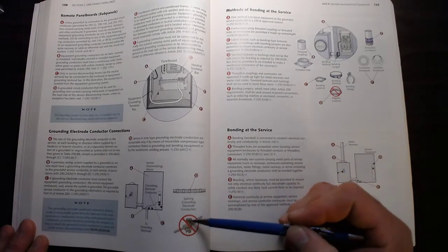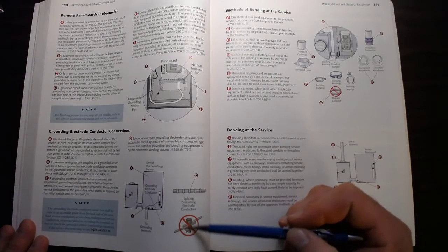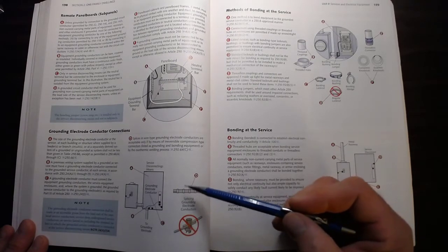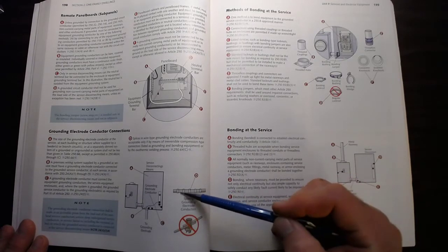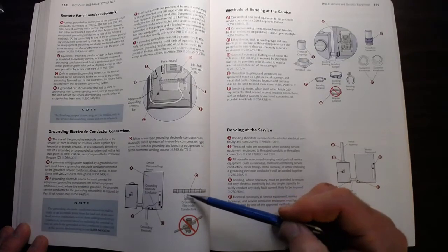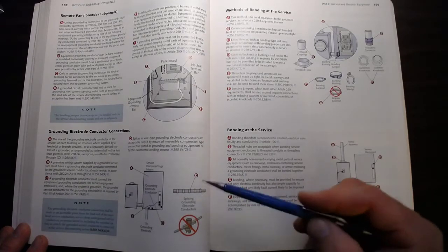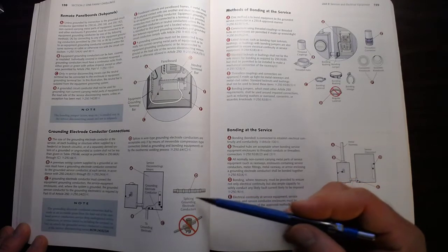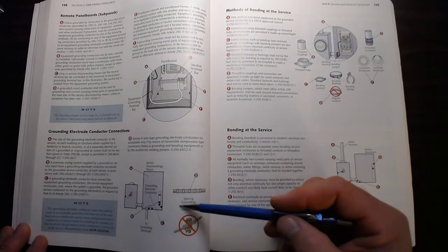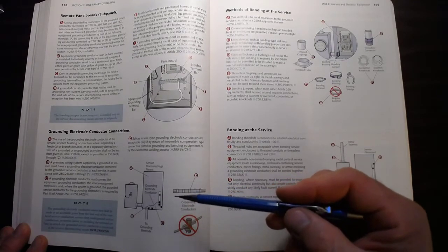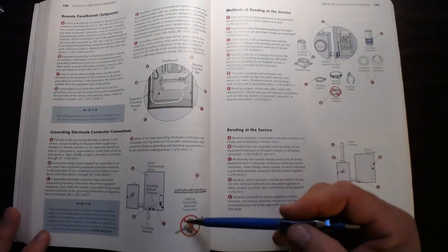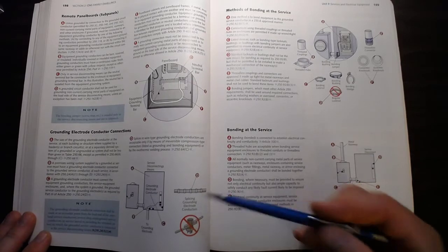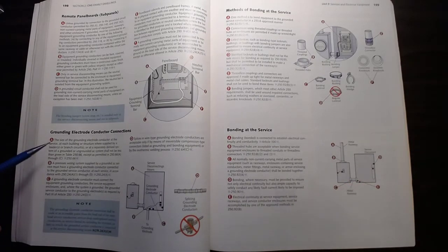You cannot use a mechanical bolt connection like this here. Or you can use exothermic welding process, which actually welds the two pieces together. A little bit more expensive to do that for residential, but in commercial you would use exothermic welding techniques to connect copper wire to a copper bus bar, a copper ground rod, or to rebar that's going to be encased in concrete.